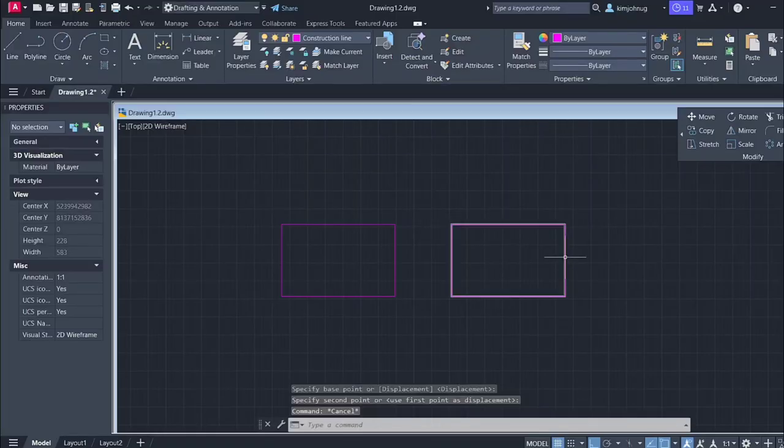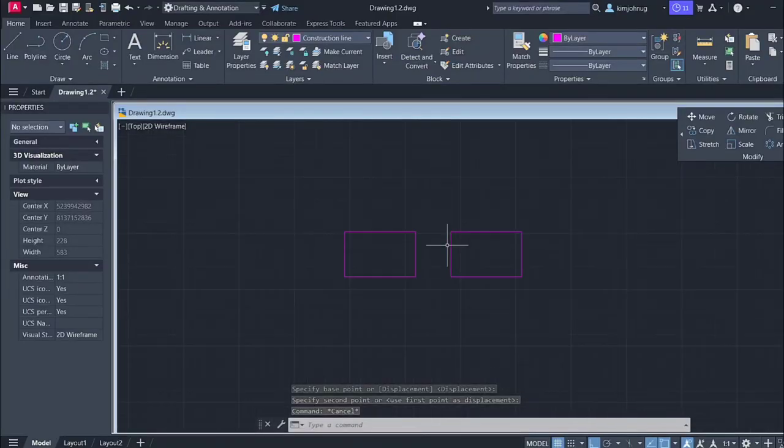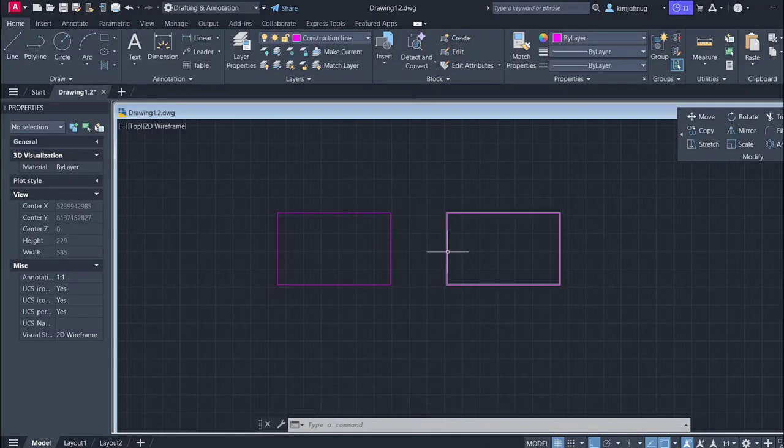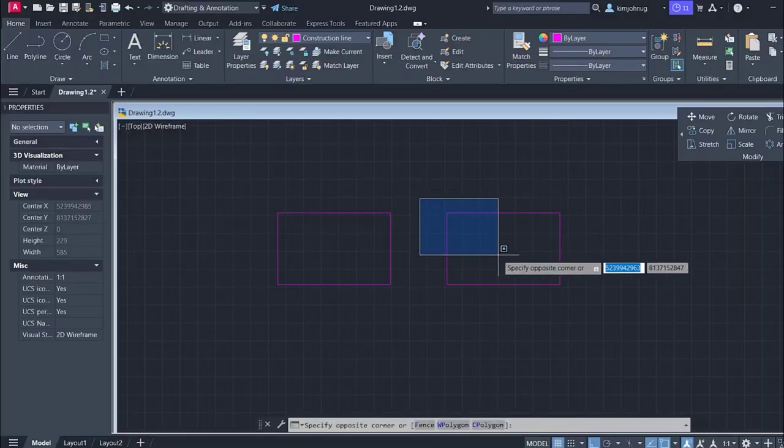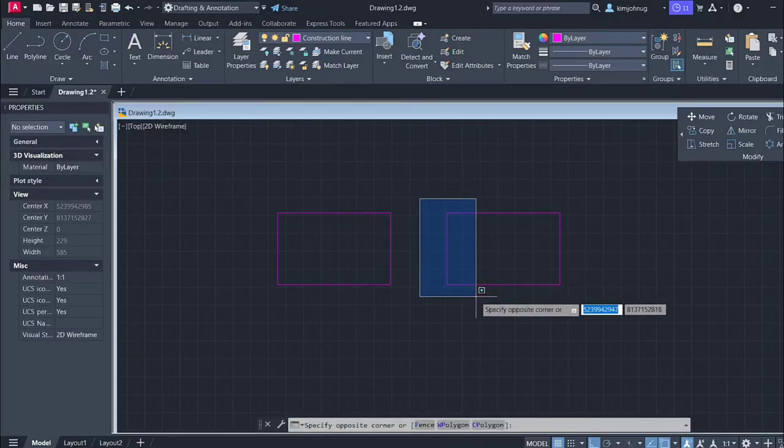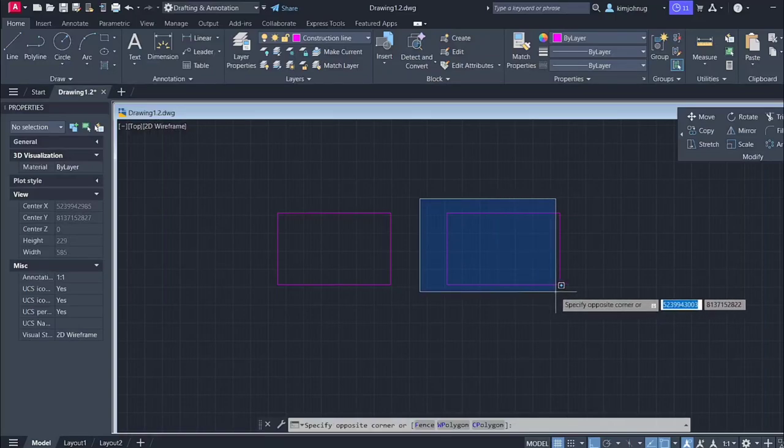But if I want to move just one line, what do I do? So maybe let me show you how we use the select tool. So select using the left mouse button. You either select from left to right, which shows a blue selection, and it selects an object if you complete its entire framework.